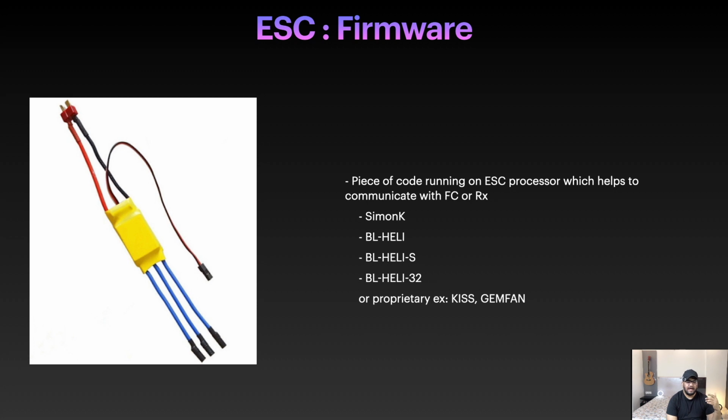Because your plane has an airfoil, it can soar and keep itself in the air without any power, so it can do some gliding. But in the case of a drone, you need very precise control, so you want your motor to stop as soon as you cut the throttle. This facility is available in BLHeli firmware. It's called active braking or regenerative braking. So that's the major difference.